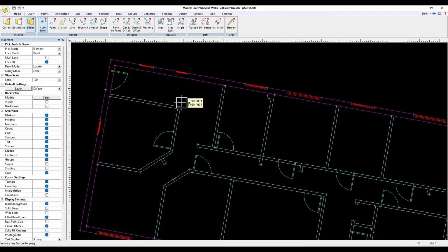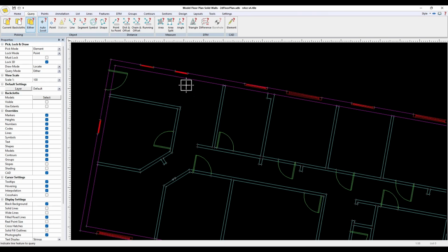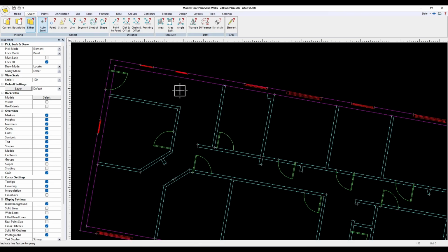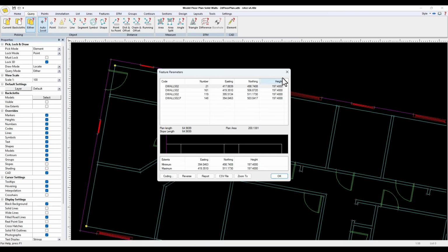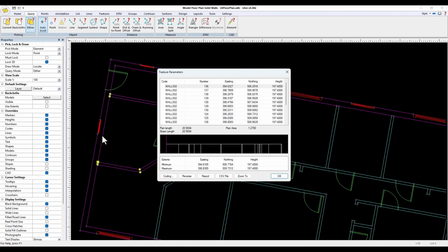So once I generated the points from the CAD data, I had to re-edit the data because I hadn't drawn it up for this purpose. So I had to make sure that the outer walls will have their own codes. I use O walls for that. Okay, and the logic basically is that the odd number wall is cut into by the even number wall. Okay, so in the code, this will be extruded based on a variable up to the height of the building. Okay, and then all the other walls can then just be extruded themselves because they are a self-contained polygon.